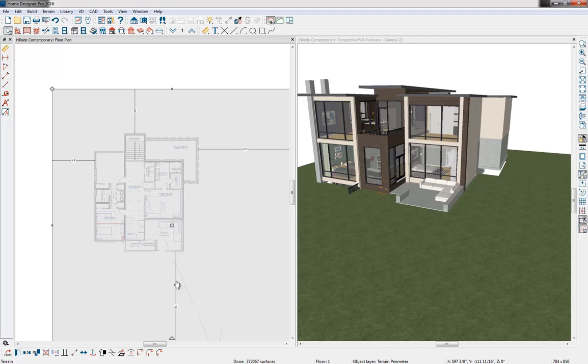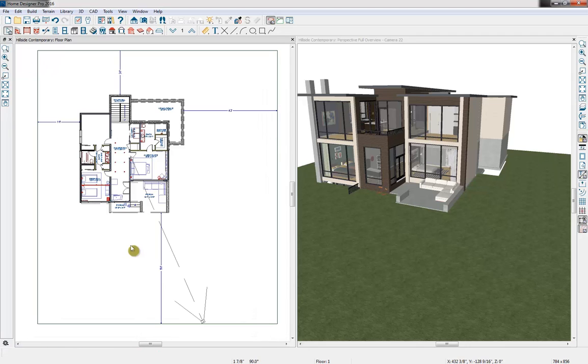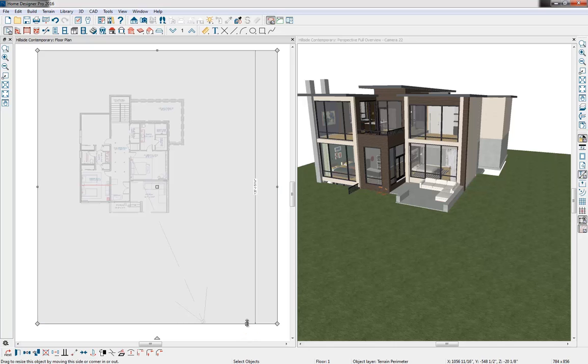Alright, so now we have everything set here. I'm just going to single click on these dimension lines and hit backspace on my keyboard, so I'll delete those for now. You can also modify the shape of this. If I've selected the bottom edge here, you'll notice that we do have some different controls in our editing toolbar at the bottom. One is Change to Line or Change to Arc.